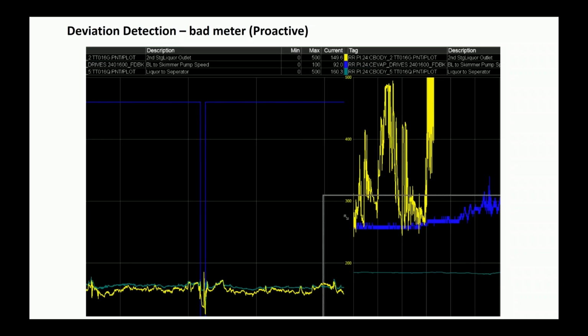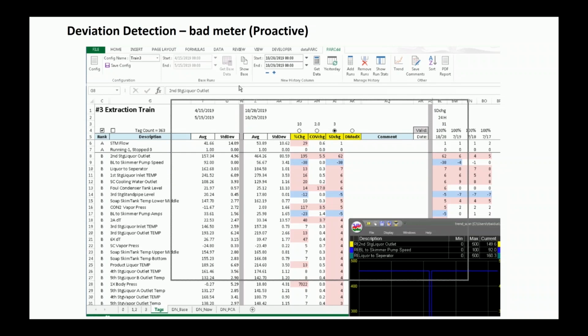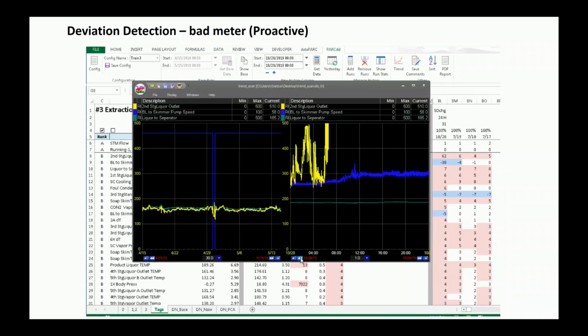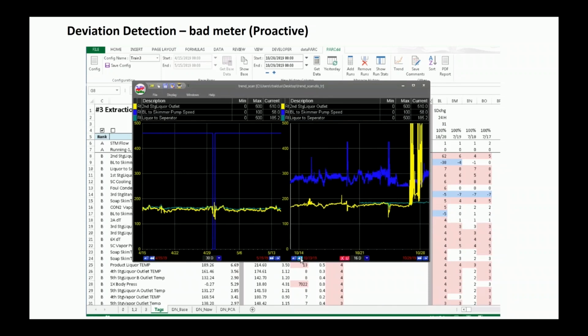And it shows you the 3 tags from the base period on the left, 3 tags from the current period on the right. Now I'm going to double back in time because that was only 1 day. And I go to 16 days on the right-hand side. And I can see the yellow tag, the one that had changed value of 62. Its temperature is 510 degrees, impossible. And sure enough, I was just curious, how long ago did we lose that temperature probe? How long has it been acting up? And it's really recent. It's just been the last couple of days.